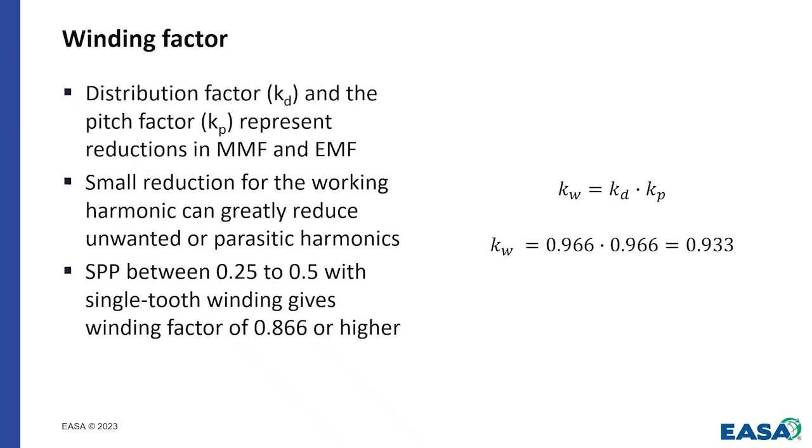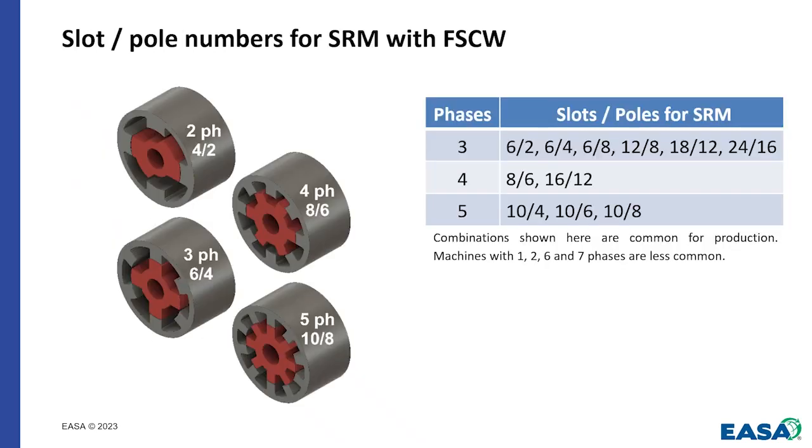When we are working on something like a 36-slot 4-pole typical lap winding, and we short pitch that coil and have a chord factor of say 0.941 or something like that, we lose about 6% of our fundamental voltage, but we can eliminate very large percentages of some of those harmonics, especially the fifth and seventh. So that is targeted. That's why we chord those standard lap windings.